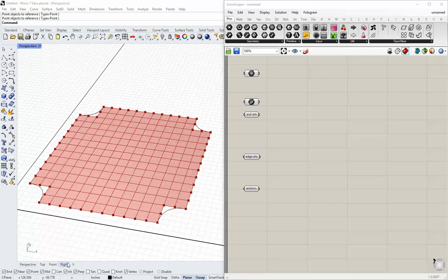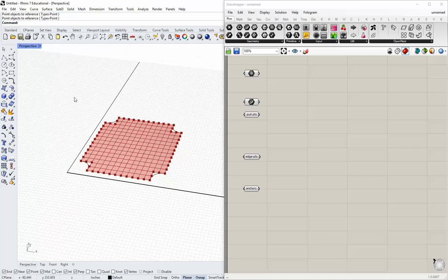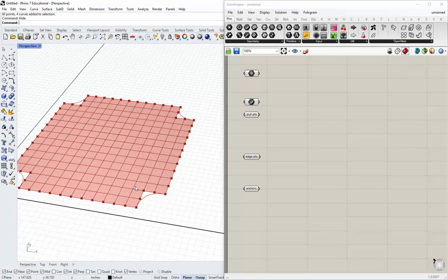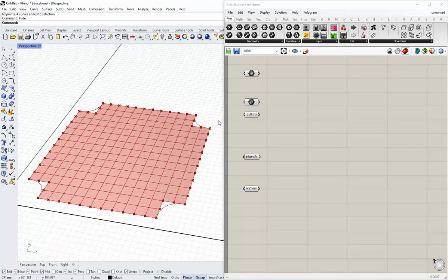So if you're starting with a file of your own instead of the base file, make sure that you're reproducing the geometry we have here and also making sure you're in inches, because the entire rest of the tutorial will be based on that. Okay, so let's keep going here. Let's start bringing stuff in, and then I'm just going to hide what we have on screen there and hang on to it just in case we need to make any edits before I internalize.